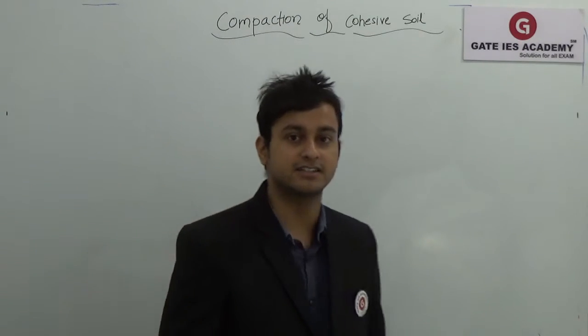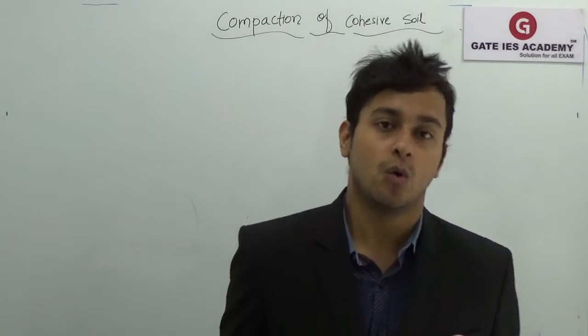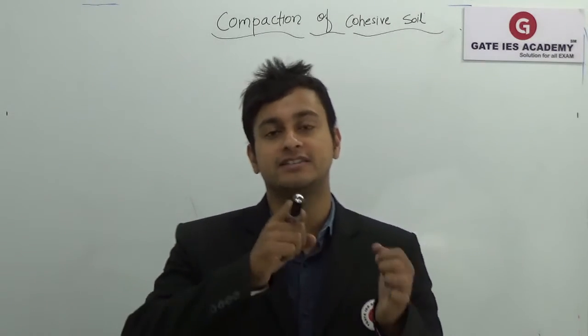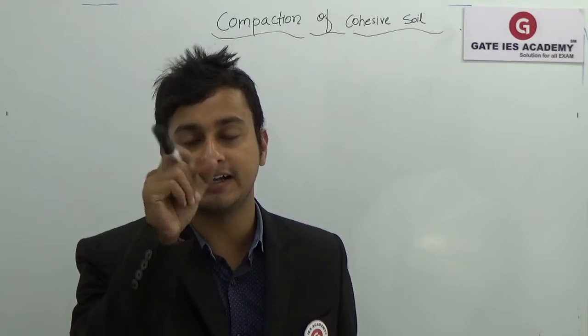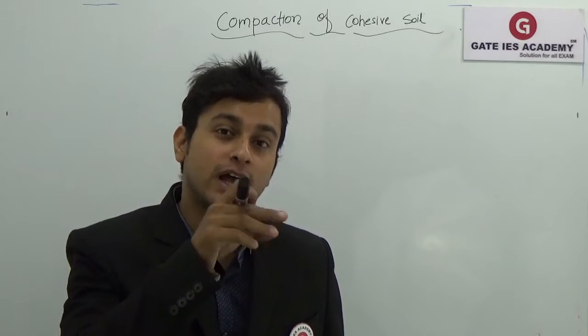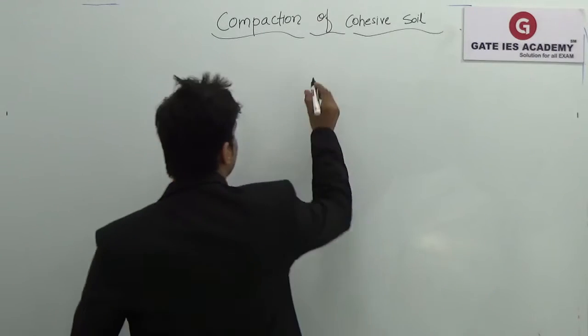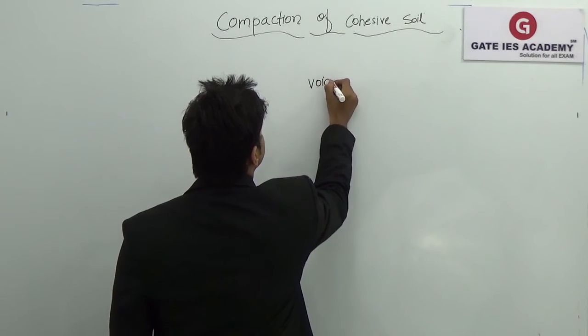Okay students, now let's discuss the compaction of cohesive soil. What is a cohesive soil? It is actually sticky in nature because there is cohesion between the particles. That is why these soils also have smaller void sizes. So in cohesive soil, void size is less.